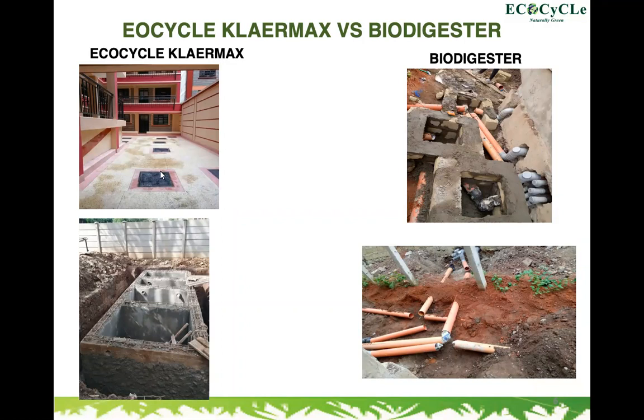So the toilet waste is separated from the kitchen and the laundry. So for every single manhole that we have going to EOCYCLE, for a biodigester, you will have double. One for the gray water and the other one for the black water. So if we have quantity surveyors in the house, you can see the manhole network alone would double a BOQ item, because instead of all the wastewater flowing in a single network of manholes, for the biodigester, it's double the manholes and double the pipe work.